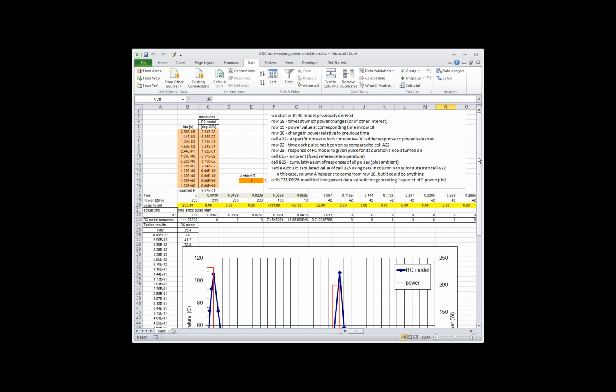But square root of t isn't necessarily what you need. You might have a physical model that shows that the linear roll-off in time is right, in which case it's a matter of choosing the right time constant and letting your RC model actually do what you want it to do. But it's a choice, it's trading off time constants, and the summation of the amplitudes over the tau for the rungs of the model to get the short time response you want.